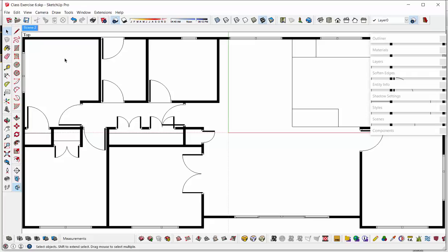So one thing that might be helpful is if we add color to the floor plan, because if you add a specific color in here, then you can select it more easily in Photoshop, because the magic wand tends to work a bit better with colors.